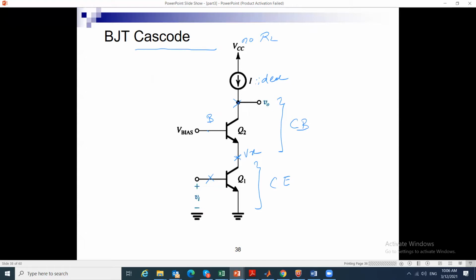If we want to call this level 1 or stage 0, okay, if this is a stage, we want to call it 1, because we called all of this stage 1, I can look at the gain from this point to this point on condition that I know what is the effective resistance seen looking outside.